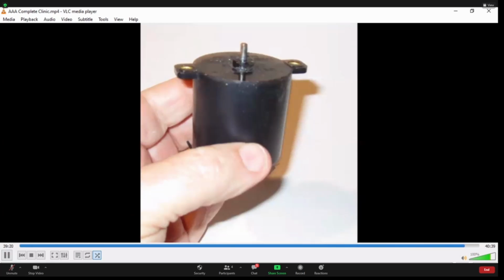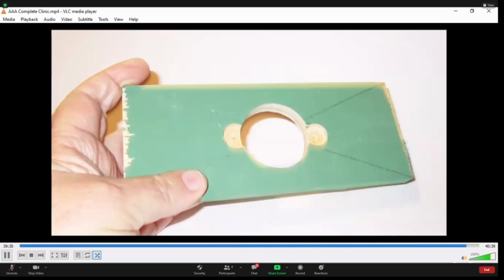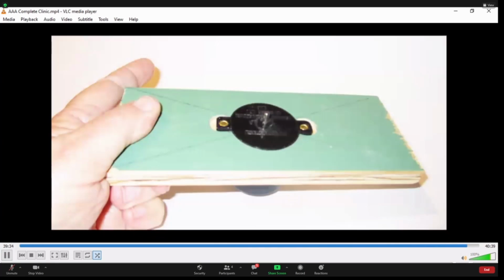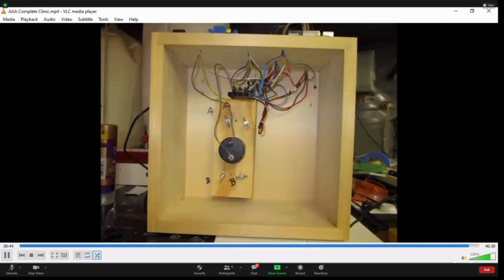And again, the mechanicals can be found at the website. Without going into the details, I drilled a 1 3/4 inch hole in the layout. I made a mounting block out of lumber and drilled a 1 3/4 hole for the motor in it. I aligned the hole in the layout with the hole in the mounting block, clamped them, and drilled 4 holes for machine screws, aka bolts. The mounting block is separated from the layout bottom using spacers.